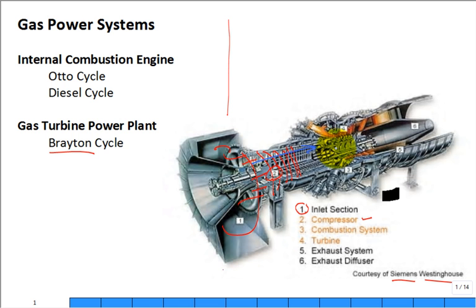Okay. Then once it goes through the compressor section, you have fuel added to it in a combustion section. Often there's a number of cans that go around in a ring. Now you have hot, high pressure exhaust gases. You pass it through a gas turbine section. It's often fewer stages, but the same concept as the compressor, having stators and rotor blades.